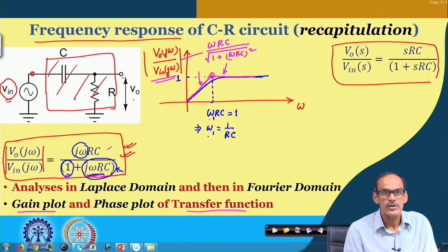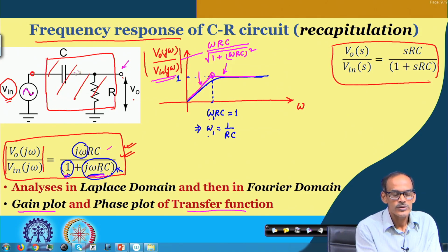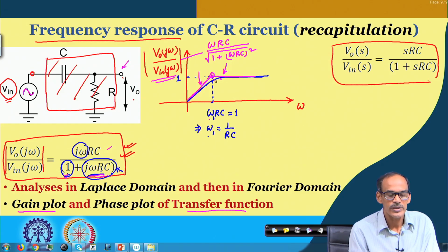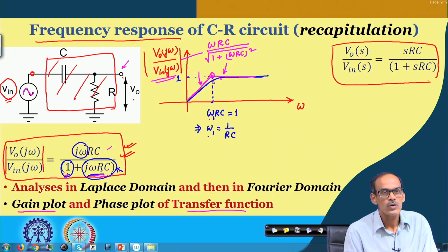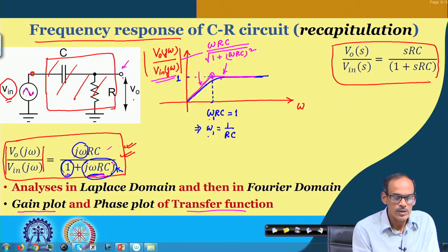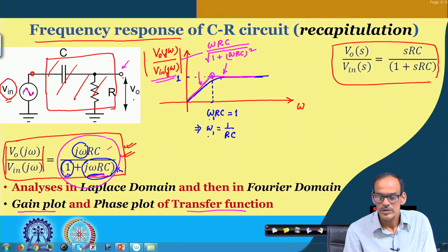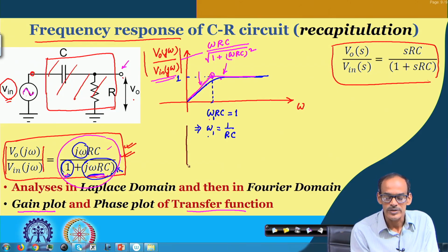Now, since it is a complex number, if we give a sinusoidal signal here, at the output, while it goes through this system, not only may its magnitude change because of this magnitude variation, but its phase might also get shifted. That phase shift can be captured by considering the phase. So, next to the gain variation with respect to omega, we can also observe the corresponding phase variation.